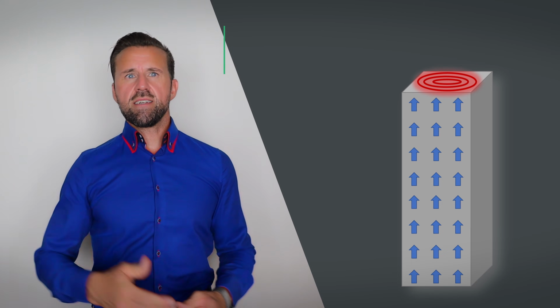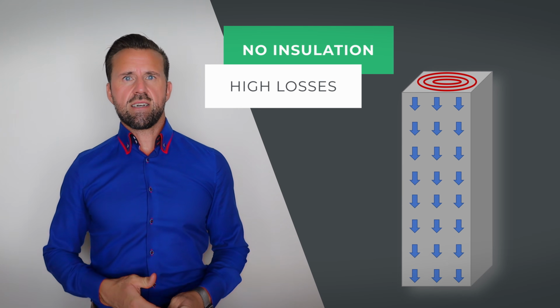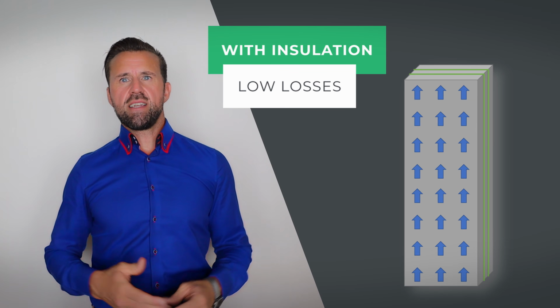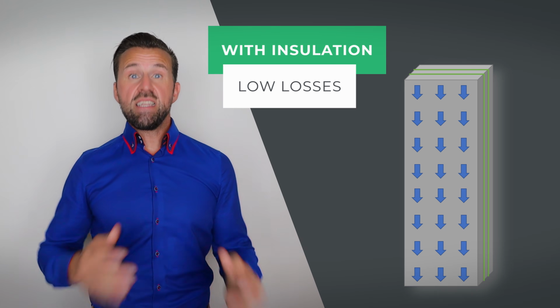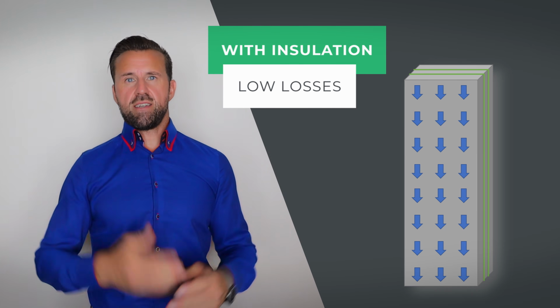In order to keep the losses low, soft magnetic materials such as electrical sheet with a small hysteresis curve are used. Eddy currents occur when the magnetic flux in the stator is changed. The eddy currents generate losses in the stator and heat the stator up. To reduce losses, the stator is divided into separated sheets, insulated from each other. This reduces the eddy current losses significantly.